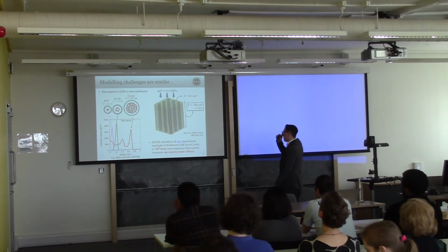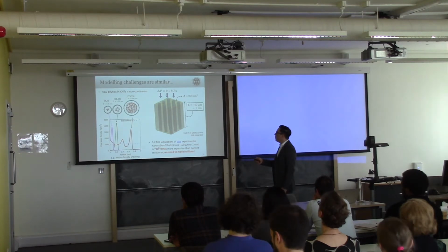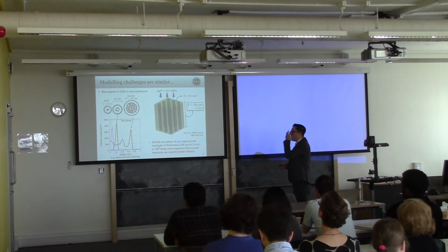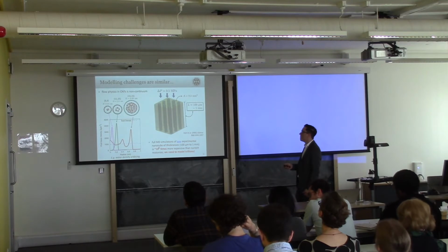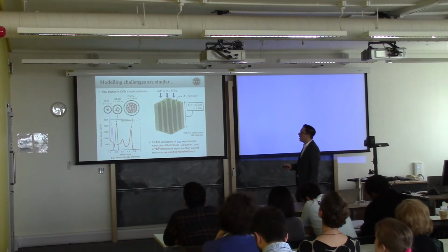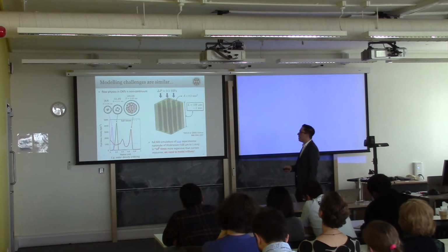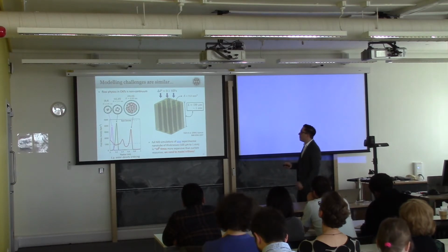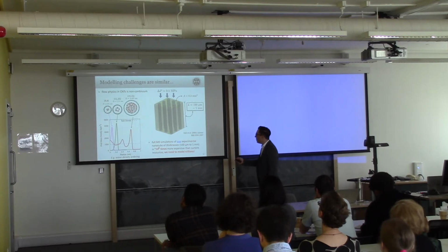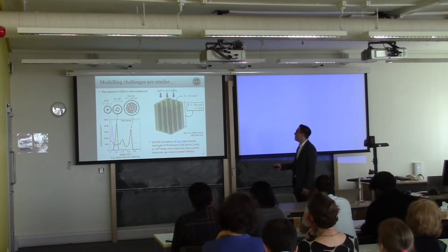And again, the reason why this is so challenging is if you take just one of these nanotubes that we're trying to solve in a membrane, the CFD doesn't apply because we have all these non-continuum effects, like the ordering of the molecules, for example. These are the sort of nanotubes we're talking about, with perfect rejection. And you can see, if we look at the density, it's 4 times what we expect in the bulk. There's also this ordering that cannot be captured by a CFD simulation. And this one tube, to do this with molecular dynamics, would require hundreds of years to solve.